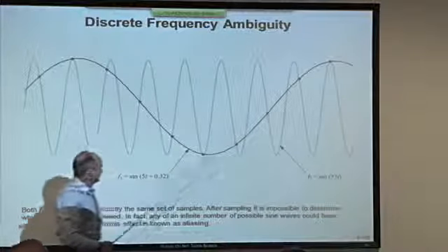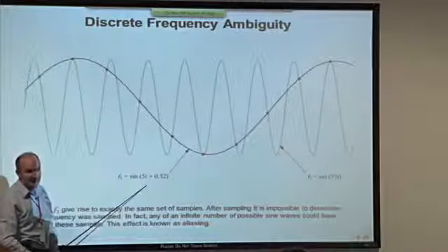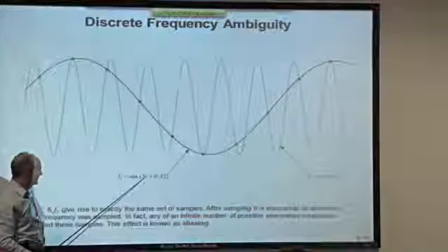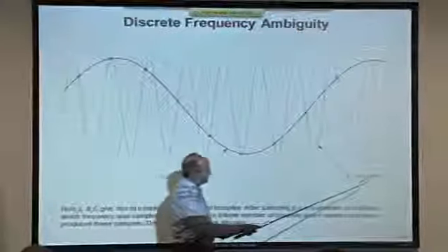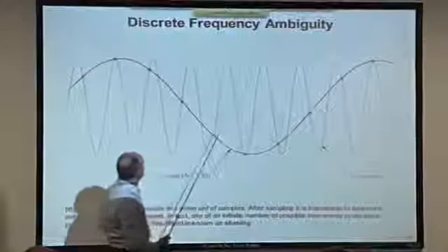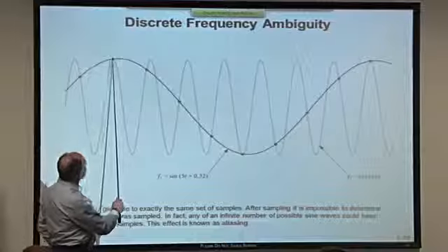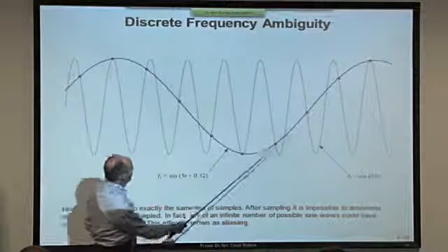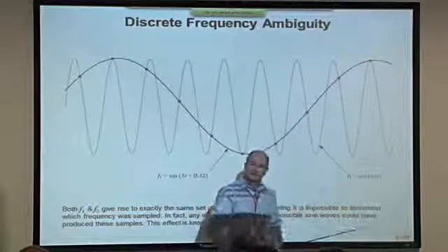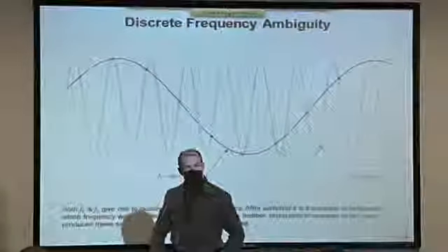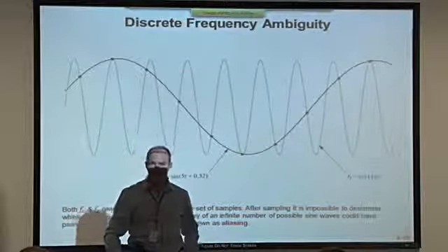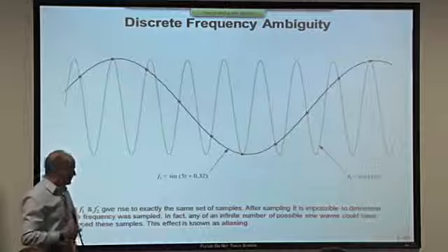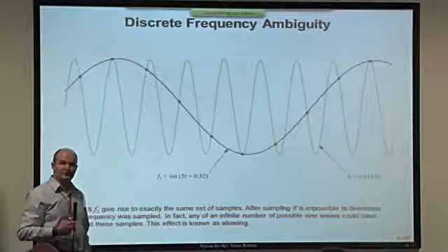Well, one of these sine waves has a frequency of 5 hertz and an inconsequential phase shift that's just there for decoration, 5 hertz, and the other one has a frequency of 35 hertz. What about the sample rate? Well, you can kind of get that by measuring the samples from peak to peak. So we've got 1, 2, 3, 4, 5, 6, 7, 8 samples on a 5 hertz sine wave. It's a 40 hertz sample rate, 40 samples per second, if you like. Now, clearly, 5 and 35 hertz look the same when sampled at 40 hertz.